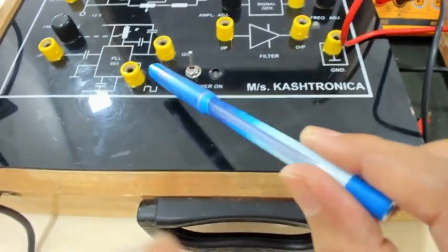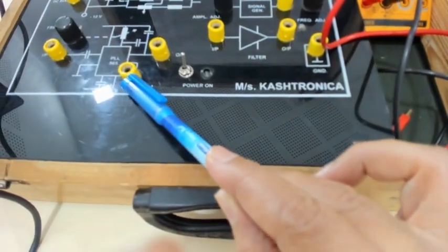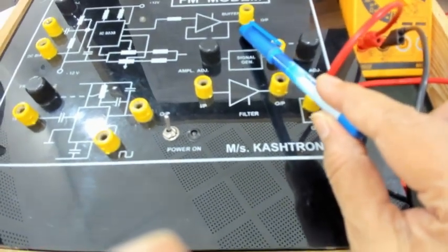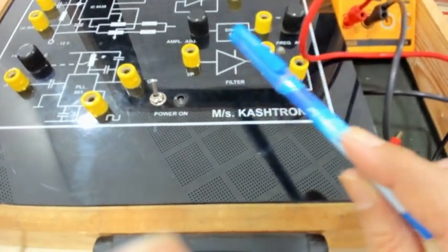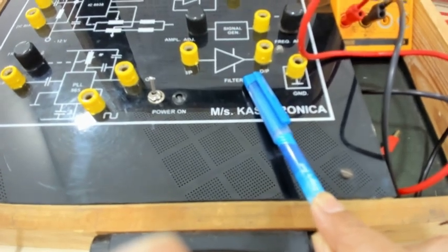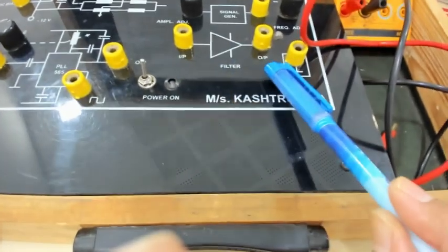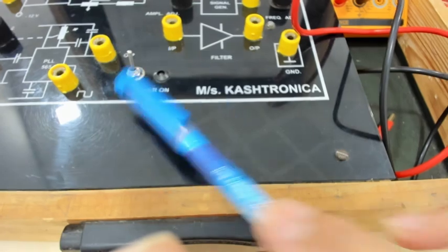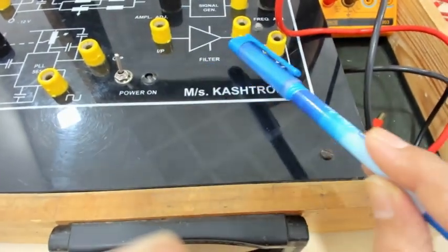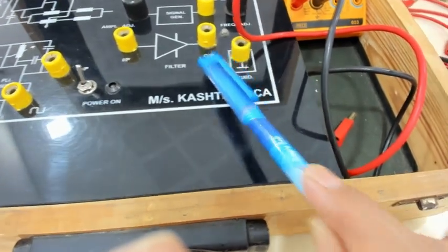Now this is your detector part, that is the receiving end, and here you can see this is the PLL 565 phase lock loop, whose frequency we have to adjust to the carrier frequency. Here we are setting it to 50 kilohertz, and this is a low pass filter which is used for removing the distortion from the output detected from the PLL. So high frequency components will be removed and you will be able to observe the clear modulating signal at the output of this low pass filter.